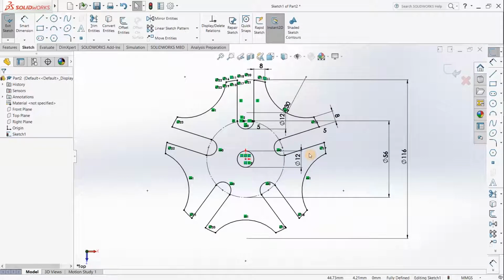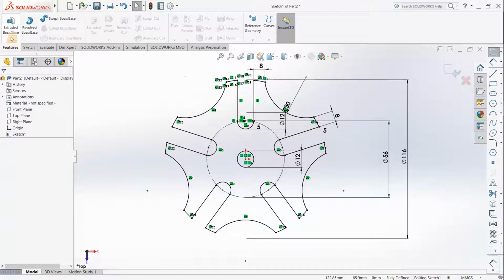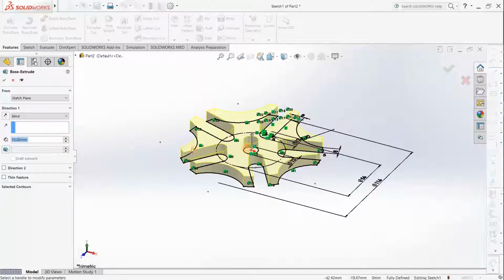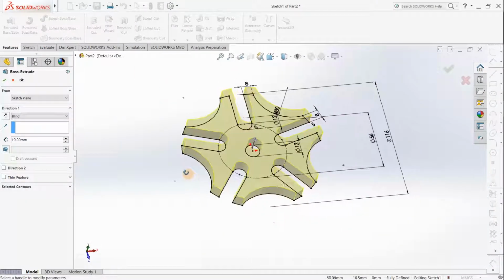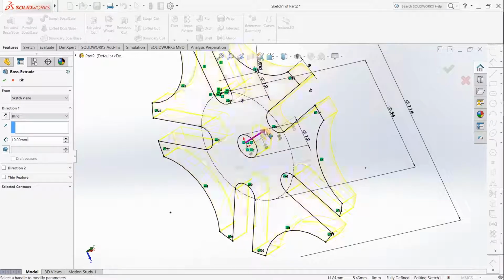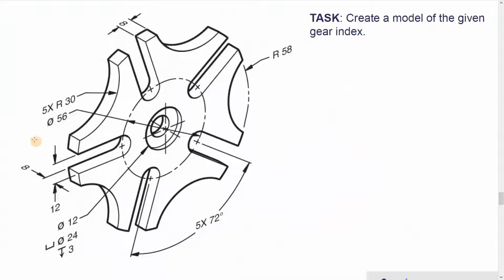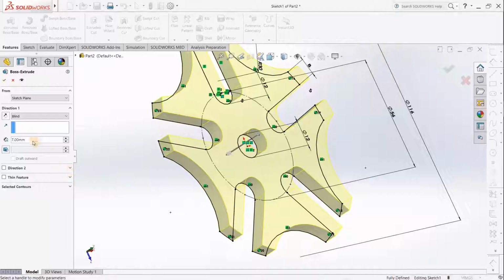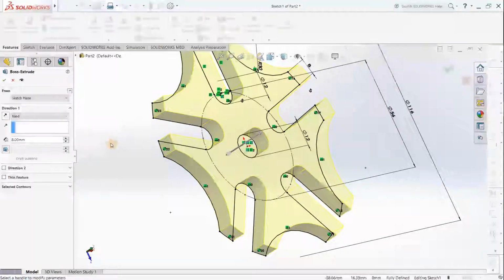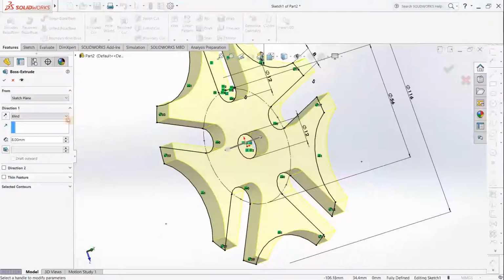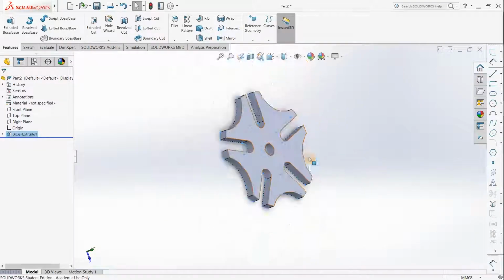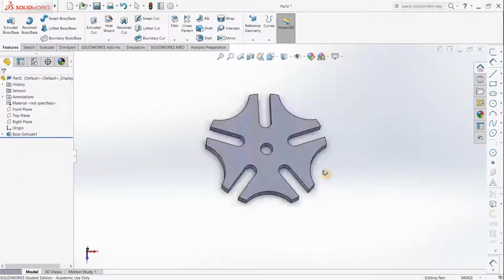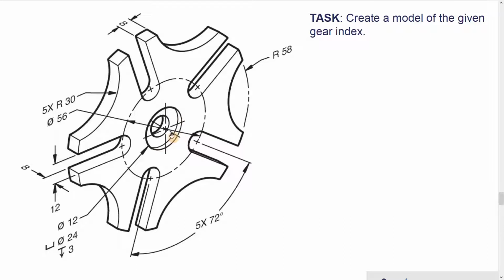So it looks like we already have enough to create a boss extrusion. We go to this menu to create our first extrusion here. As you can see, it looks fine. You can drag the arrow there, but it's not really a convenient way. I prefer a direct input, so it's 8 millimeters. Well, that looks fine. I'm gonna click OK, and let's do the last step.